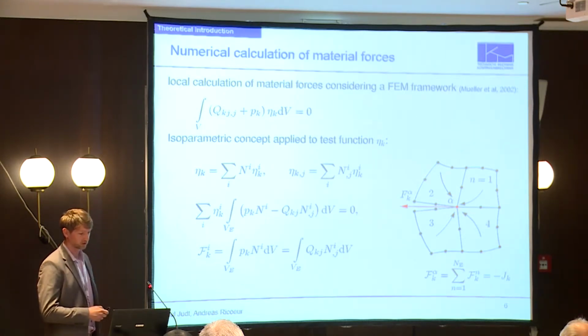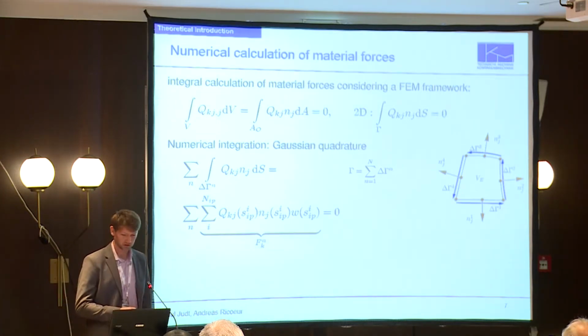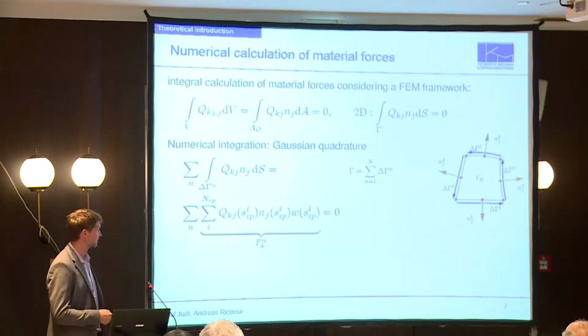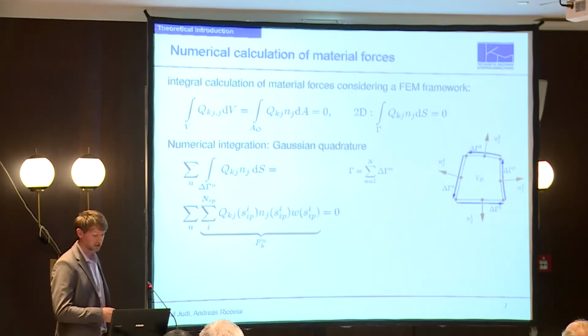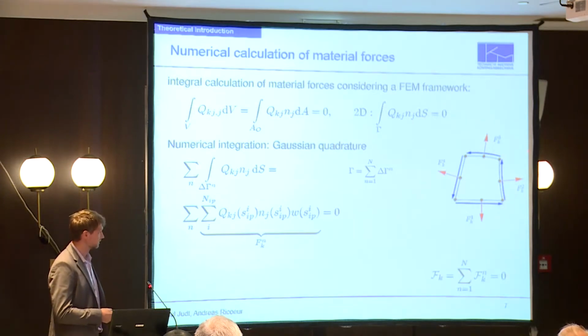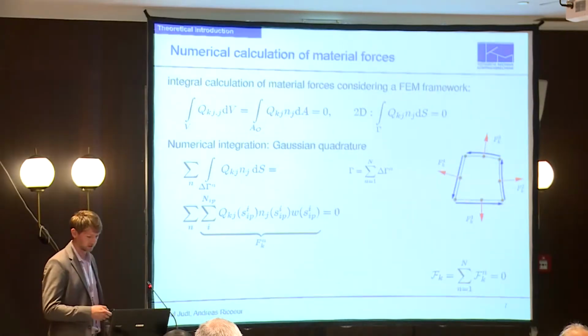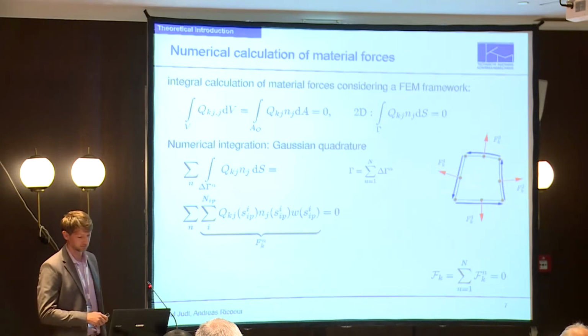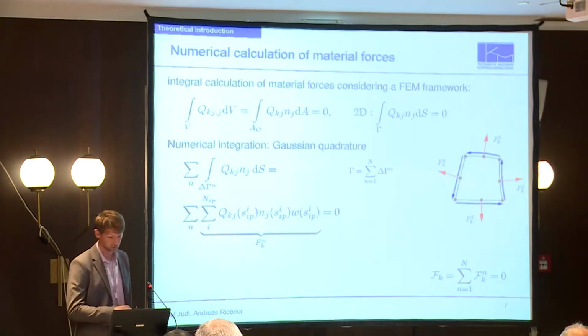Other than this local approach, one can also apply an integral calculation for calculating material forces. For example, one can use an integration path along element edges. So one obtains material forces resulting from these integrations, and of course, as this volume is defect-free, again our equilibrium holds and the sum of these forces is equal to 0.